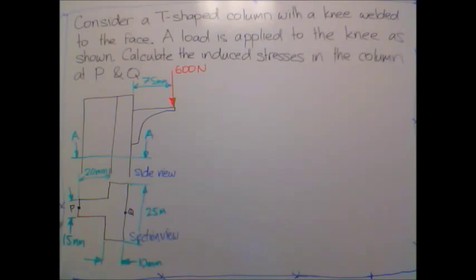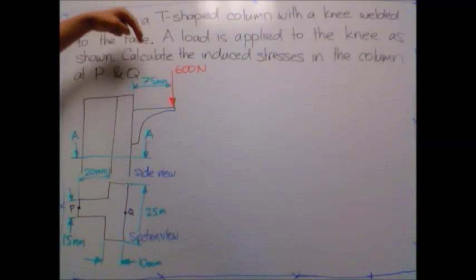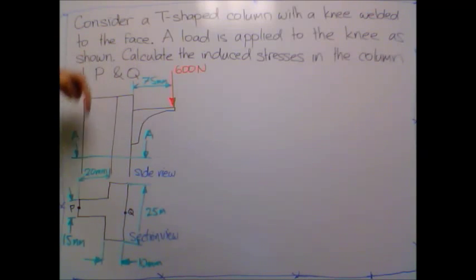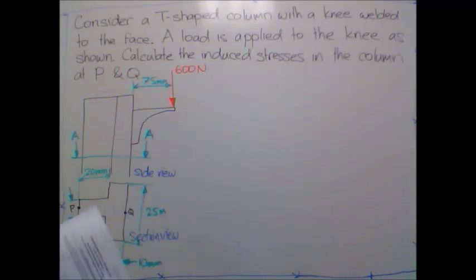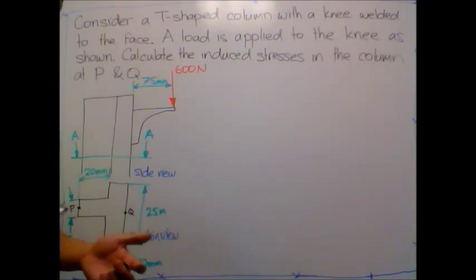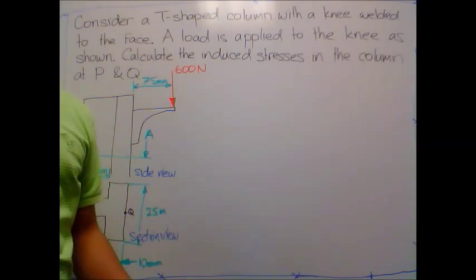And we'll also need information about the cross-sectional area to find the stress due to the direct load being applied on our section. So let's get started. Our first step is to find the centroid. There are 2 ways we can find the centroid, and both of them use the same formula. I'll use the formulaic method for this.